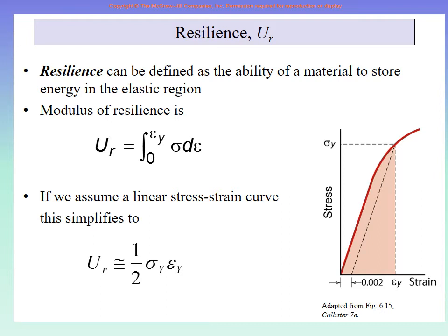Of course, it is elastic, so when you remove the force, then the material goes back to zero deformation. You can increase the load until you reach the yield point. So as long as you are just below the yield point, the load is very high, there is quite some deformation, but as soon as you remove it, all the deformation is gone, right?